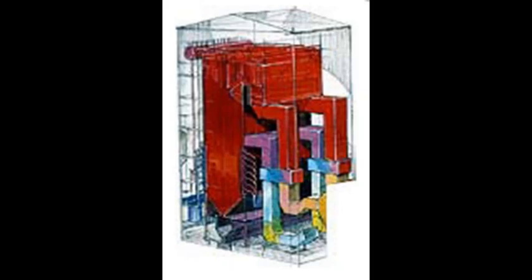In boilers, we provide this oxygen through air. As I have already mentioned, some air is used as primary air, utilized for conveyance of coal up to the furnace, and some air is utilized for completion of combustion, which is called secondary air.